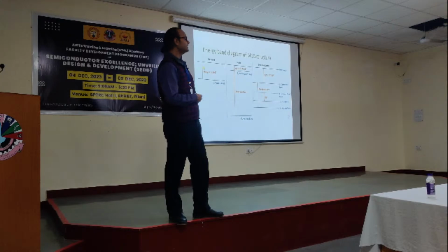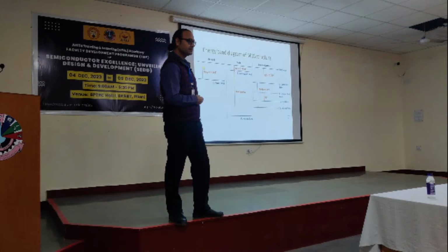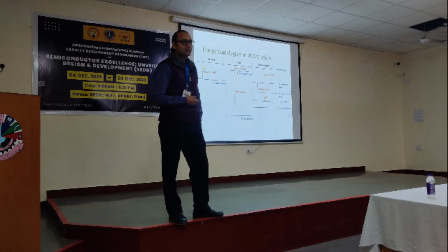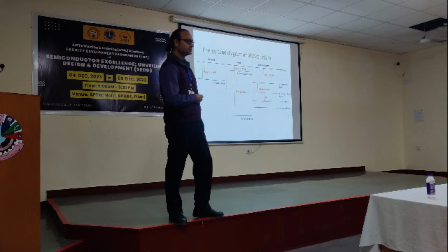So the only change will be that. Suppose copper has a larger work function, right? Suppose it goes up to this point. Then the same process will take place again, but the band bending will go on reducing. Then the Fermi level will change, around 4.5. So shift this line accordingly, and now you can see this Fermi level and this Fermi level will come closer. Sir, the Fermi level will be nearly equal to the valence band, right? Nearly or equal to the valence band.